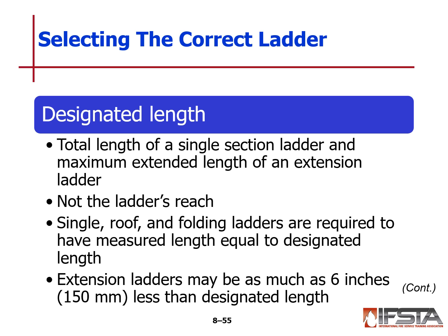Total length of a single section ladder and the maximum extended length of an extension ladder. You want to note the ladder's reach. So set at that 75-degree angle, what will this ladder actually reach to?